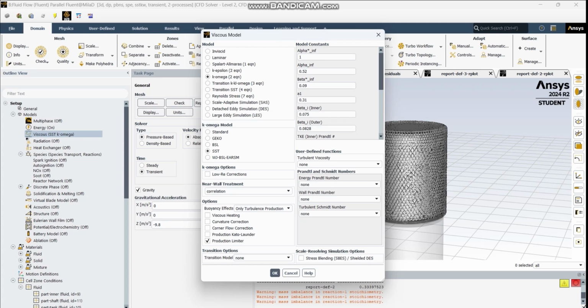In computational fluid dynamics simulation, particularly involving stir tanks with chemical reaction, turbulent viscosity plays an important role in defining how momentum, species, and energy are transported throughout the fluid domain. When you're using Fluent, turbulent viscosity is not something we manually assign.